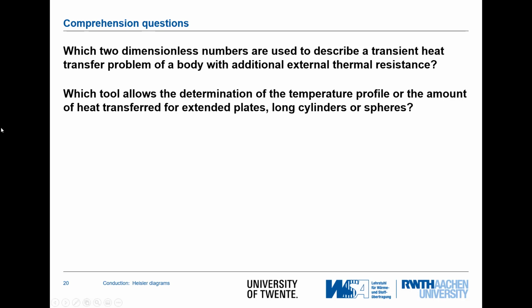Second question, which tools allow to determine the temperature profile or the amount of heat transferred for external plates, long cylinders or spheres? We have learned in this video that the Heisler diagrams can be used to calculate those parts. Of course, you can also use equations for that, but they are more complex, and for the sake of simplicity, especially for solving exam questions, we refer to the Heisler diagrams.